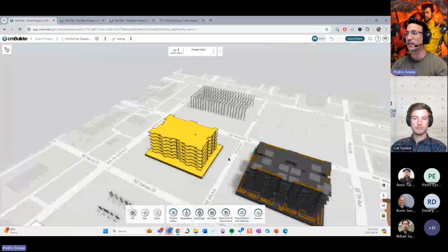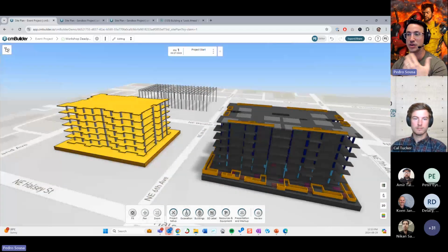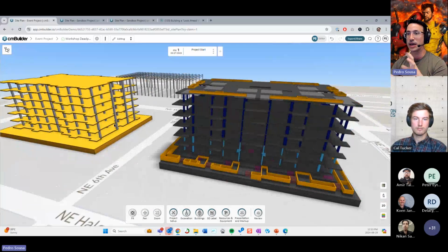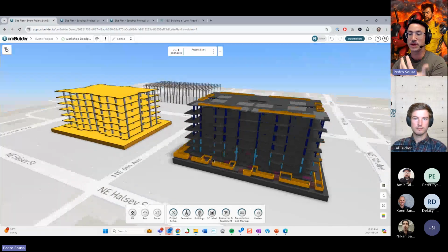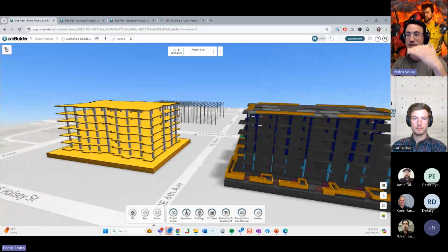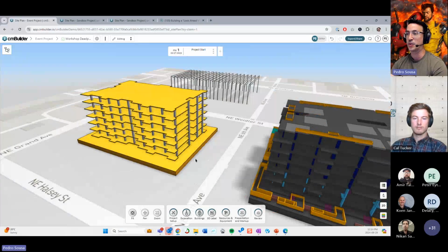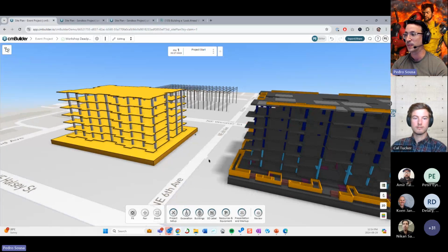And when you look at things like this, for example, where this is a building that exists and you create your massings, you can almost not tell the difference between the disposition of these columns over here and these columns over here, because they're very approximated, and they're showing the steps that you want to create. So keep in mind to balance the level of detail that you're taking out and the effort that you're putting in. Cool.